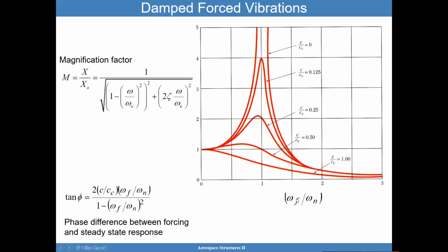So let's look at this carefully. If omega f is very small compared to omega n, then you're going to see that the amplification is almost nothing. In other words, if you were to apply the load almost statically, that'll be good enough.